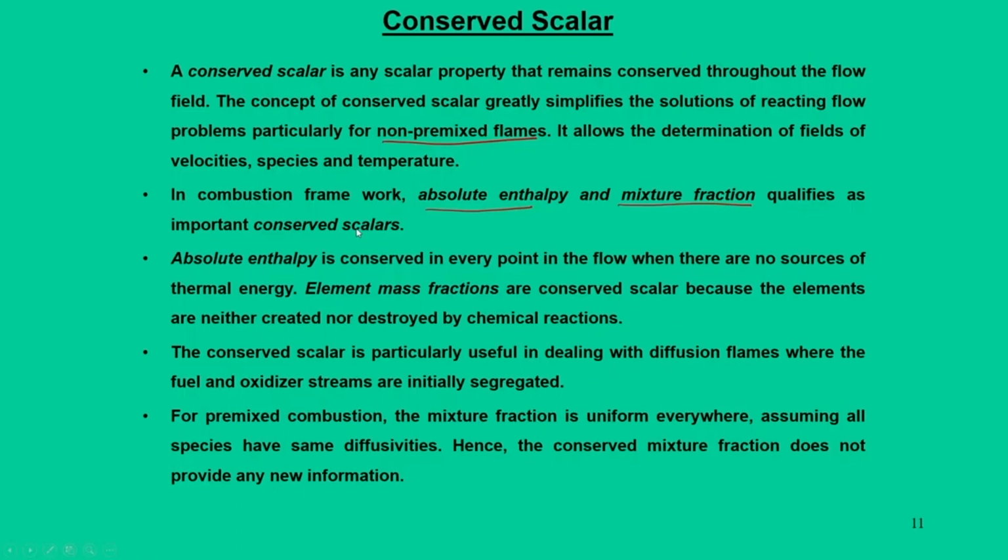With this viewpoint, we say that in the combustion framework absolute enthalpy and mixture fraction qualify as important conserved scalars. Why is absolute enthalpy conserved? Because it is conserved at every point in the flow where there are no sources of thermal energy. Absolute enthalpy remains constant everywhere because there is no source of thermal energy. Enthalpy can change, but absolute enthalpy cannot change throughout the process.